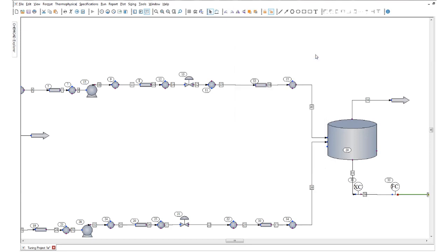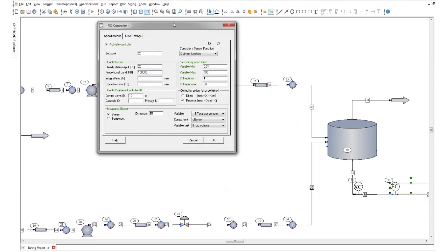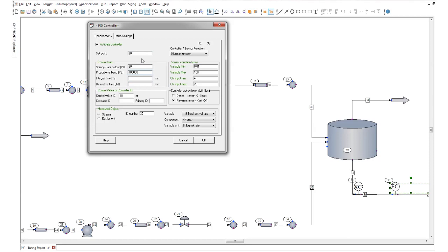And then when we're done with that, we're going to tune the water flow rate valve using the flow controller to give me the target value. So we should be able to get perhaps up to about 95 gallons per minute might be the max. But that would mean that my water flow rate and my ethanol flow rate, those valves might be at 100% opening.